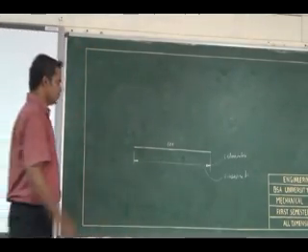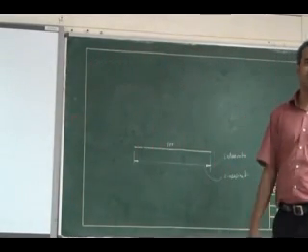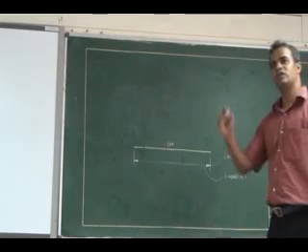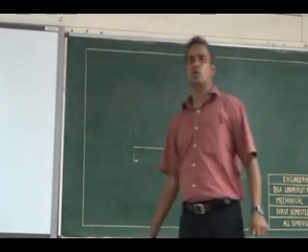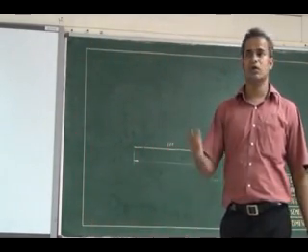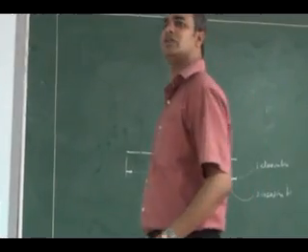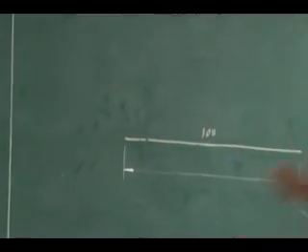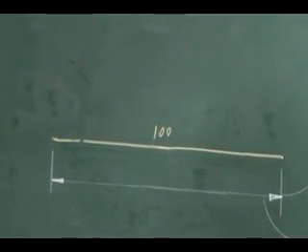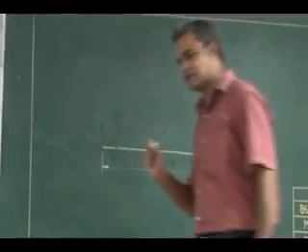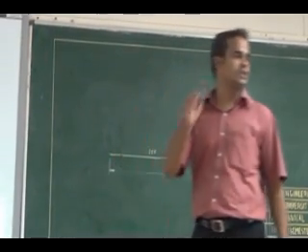Is it clear? Now coming to the arrowhead. The arrowhead is a very important one in your drawing, so you have to put your arrowheads neatly. In a drawing you can see a minimum of 20-30 arrowheads. If you are not drawing them properly and neatly, then your overall drawing appearance will go. So practice the arrowheads to draw them as clear as possible and as small as possible, but at the same time you have to maintain the ratio.